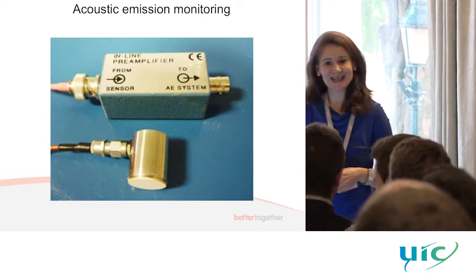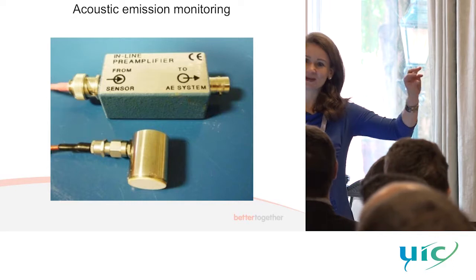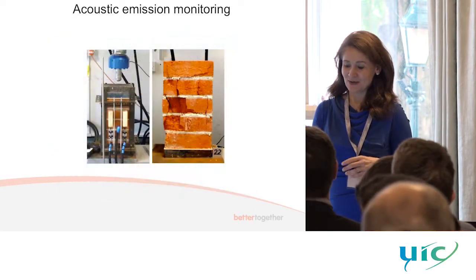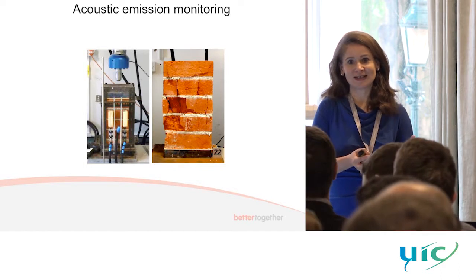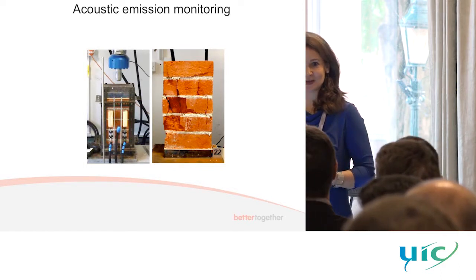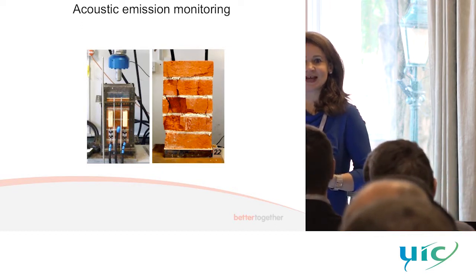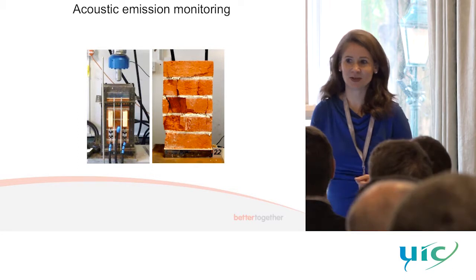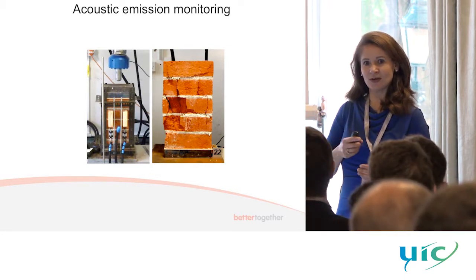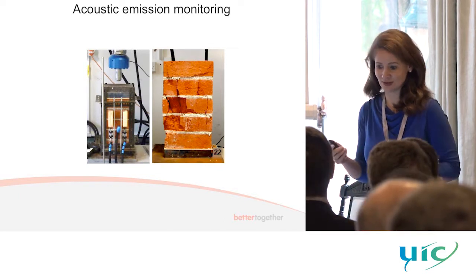Okay, right. So basically the same principle applies, putting the microphone on the structure, on the bridge, and listening to cracks. First of all, we tried testing the system in the lab at University of West of England in Bristol, or before that at Salford University, and then went out and tested some bridges in situ. So these are some examples of the process of fatigue deterioration.